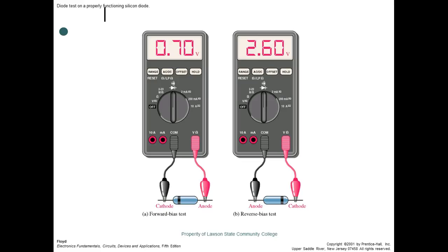Okay, so everybody okay on how to check these things? Check it with an ohm meter. And we explained how an ohm meter actually works. We still say check it with an ohm meter. But what it does when you flip it over to the diodes, we call this the diode scale, but this is what we call the p-n junction scale. That's technically what it is. So any device that's got a p-n junction, we can use this meter to check. So we call it the diode scale, but technically it's a p-n junction scale.